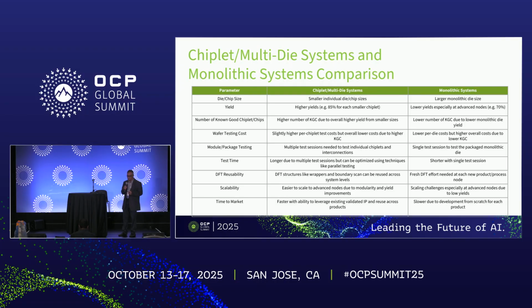So now here is a quick comparison of what we are talking about. What I'm going to bring your attention to is, when you go from typical monolithic test flow versus system in a package, we have seen a flood of test insertions increasing, as you can see earlier in the equation, in number of dies in the cost model.